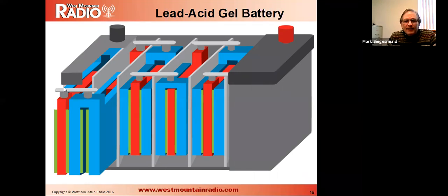What they've done is they have these patties of acid that they squeeze between the plates. So instead of flooding the whole battery, you just have these little patties of acid. It's a lighter weight battery, and you don't have to keep filling it with acid the way you do with the flooded battery. There's no evaporation here.